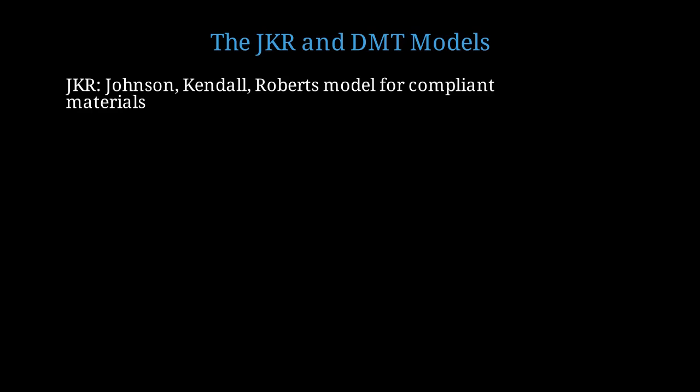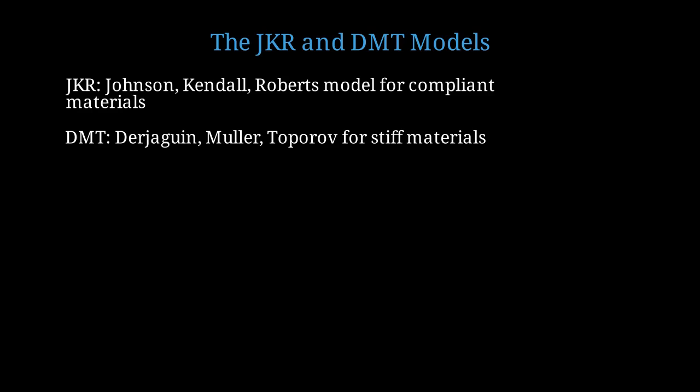Two fundamental models describe nanoscale adhesion, the JKR model and the DMT model. Both consider elastic deformation and surface energy, but they apply to different material properties. The JKR model, developed by Johnson, Kendall, and Roberts, applies to relatively compliant materials with high surface energy. Think of soft elastomers or biological materials. The DMT model, by Derjaguin, Muller, and Toporov, applies to stiffer materials with lower surface energy. This includes many ceramics and hard polymers.